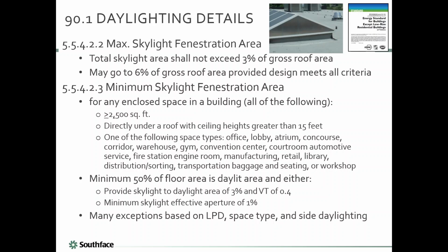And it needs to have an actual roof above it. So, it can't have the next floor above it. So it has to be sort of easy to put a skylight up there. And then it also has to be a type of occupancy or space that really is conducive to natural daylight. And, lobbies and office atriums or open offices or conference centers, convention centers. These really do kind of make sense. Retail, that's another great example.